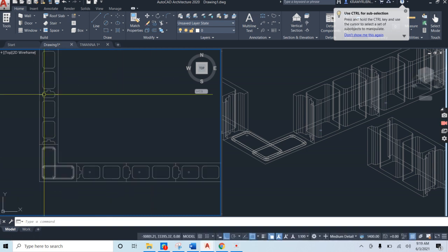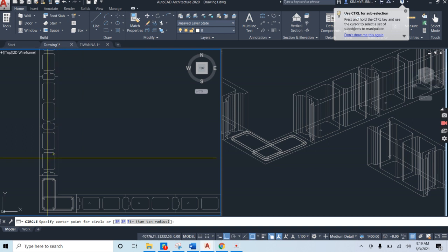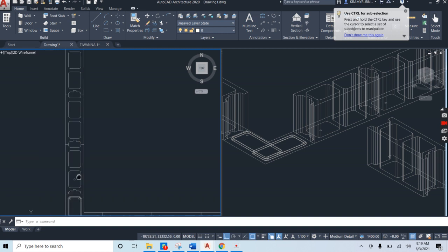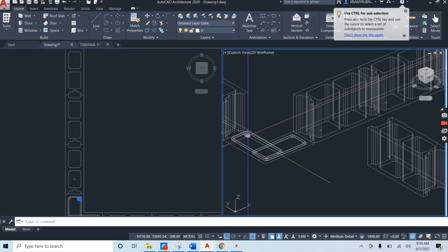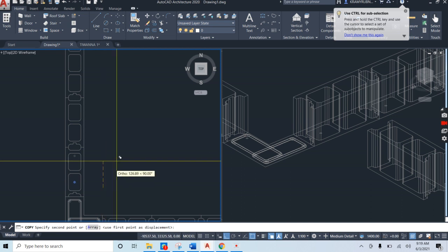Since we have also placed side walls, let us put wall bars in those as well. So circle, diameter 13, enter. First wall bar along that side. Oh, allow to now copy our bars 400 apart.